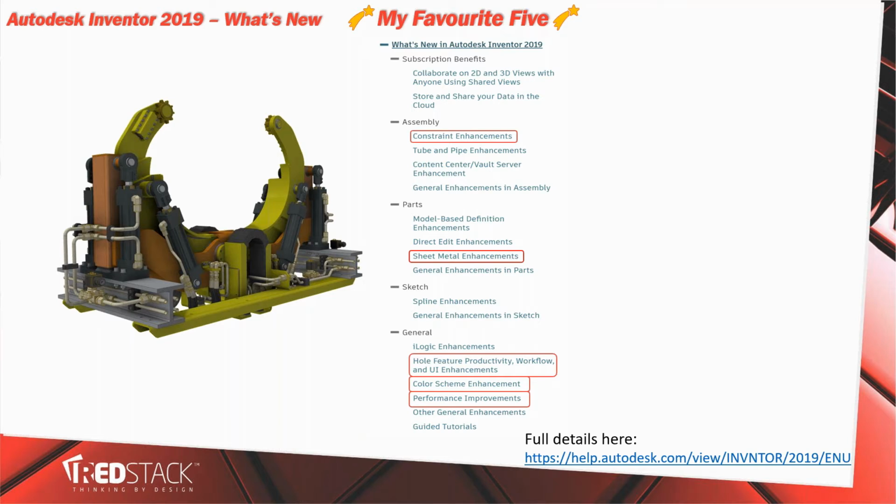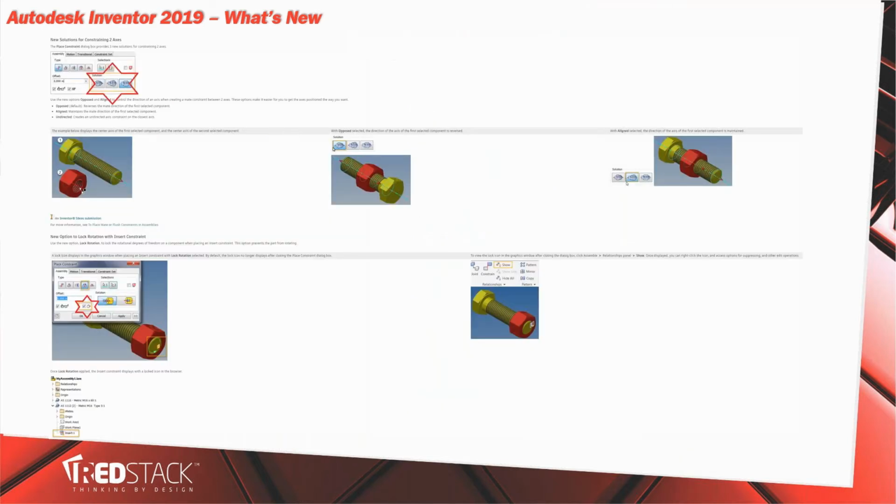So first up, Constraint Enhancements. For those of you that have been working with Inventor for some time, you'd recognise a slight change here and a nice little feature to the mate axes constraint. So if we're using a mate and we pick 2 axes, the dialog box changes now and we get these extra solutions for flipping the direction. So that's quite a handy one. I'll go through that in our live demo a little later on. A new feature there that's been added to the way we constrain axes. We can flip that direction over.